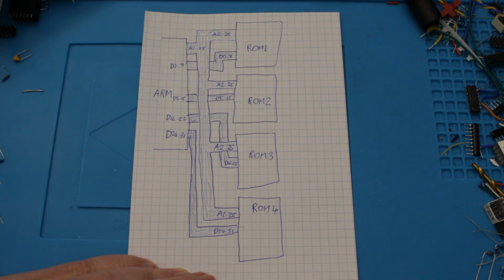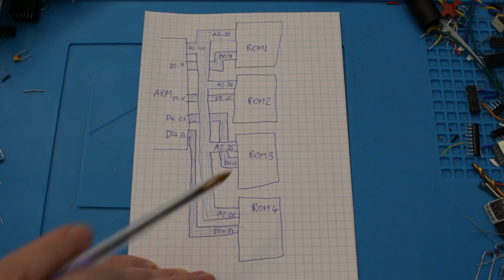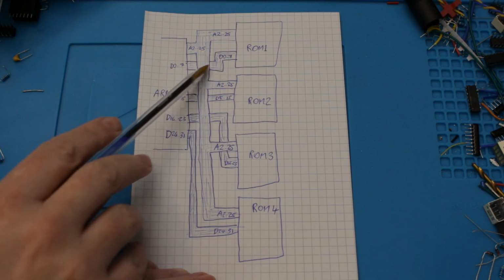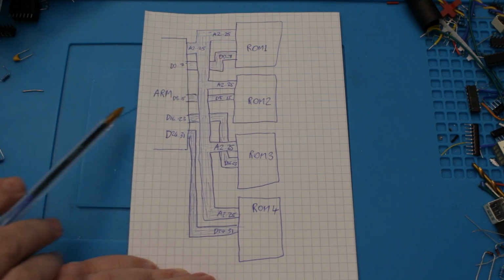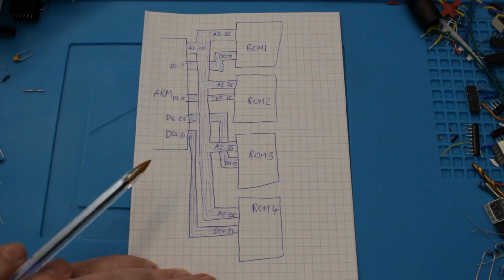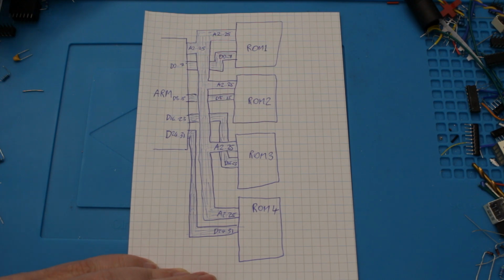And this means that when we write these ROMs, first of all we're going to need 4 separate ROMs. There's no way we could run the system with any less than 4 ROMs this way, because if we did, only the bottom 8 bits of each word would get filled in, and that's not going to work because all the ARM instructions are 32 bits wide. So we need all 4 ROMs, and indeed we also need to take our program and split it across all 4 of the ROMs. We need to send 1 byte to each ROM in a kind of interleaved sequence. So that's not too hard to do.